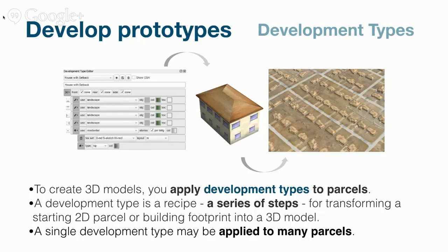Another operation, so we have split, color, extrude. This arrow on the left here is what takes the two-dimensional shape and actually creates a three-dimensional volume out of that shape. And we treat that as a building mass. So the up arrow extrudes the 2D shape into a building mass and results in two nodes beneath that. Each of these lines or steps in the recipe, we term a node. And after you create a 3D shape out of a 2D shape, you have two nodes, the facade and the roof. And this is just a very quick way to do this kind of massing model.